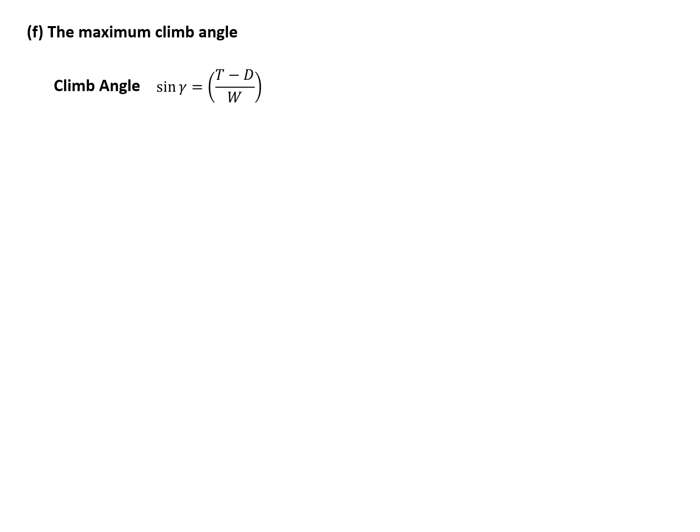The last question is a calculation of maximum climb angle, and we know the sine of climb angle gamma equals excessive thrust, and the maximum climb angle means the gamma is the largest. In that case, we need to apply D minimum into this relation. So finally, just getting those numbers, we have the maximum climb angle is 5.29 degree.